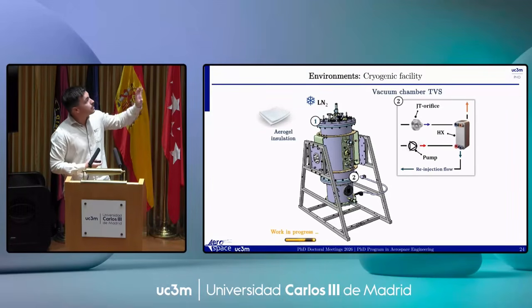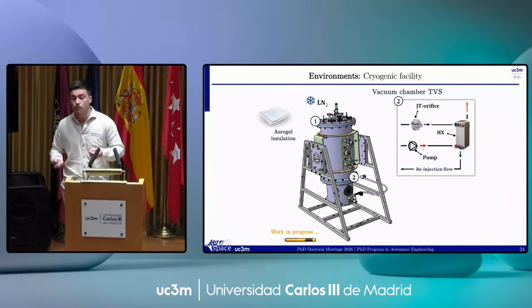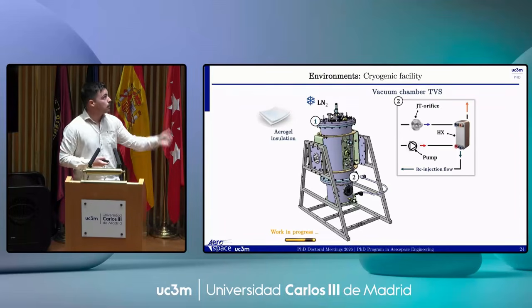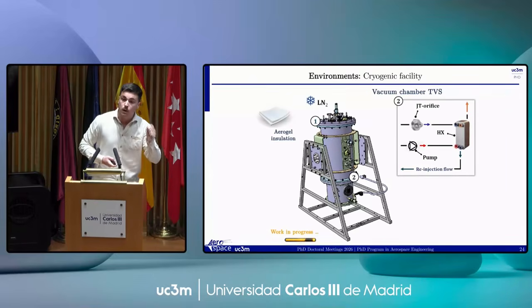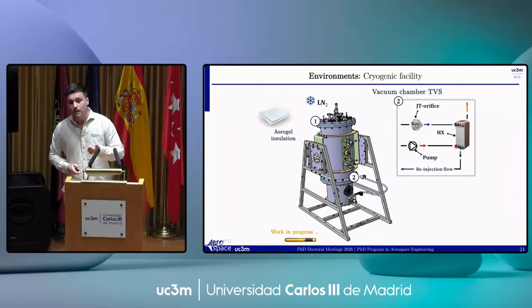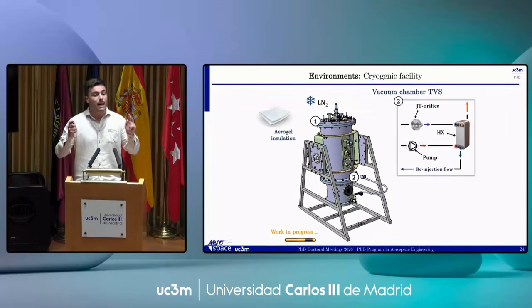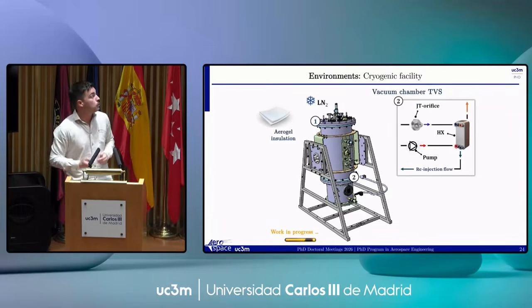And here, the idea is that we have a second volume coupled to the tank, which we called the vacuum chamber, where we are developing a thermodynamic vent system, which basically consists of an open refrigeration loop, where one stream of liquid is expanded, so it goes to a lower temperature. The other one circulates in a closed loop by means of a pump. We cool it down in a heat exchanger. We re-inject it through the bottom of the tank, mix the liquid, remove the thermal stratification, and control the pressure over time by guaranteeing that we can offset the parasitic heat ingress into the tank.